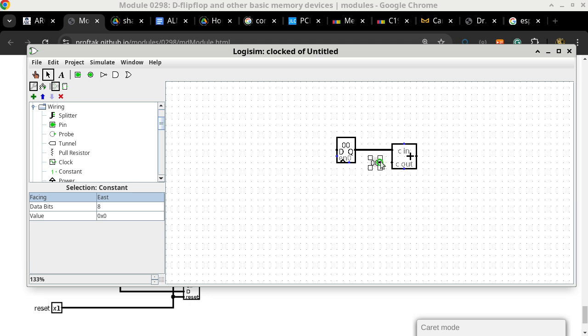So we are basically adding the output of the register with zero, but I'm going to specify a one as K0 as the carry input, because the output of an adder is technically the sum of the two inputs plus whatever K0 is. So K0 is the third component that you're adding when we specify an adder.